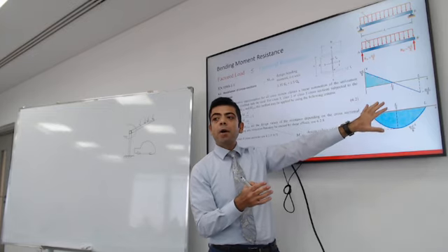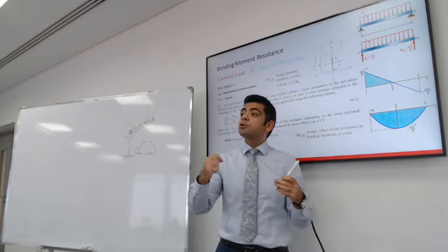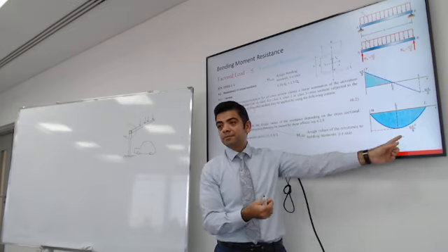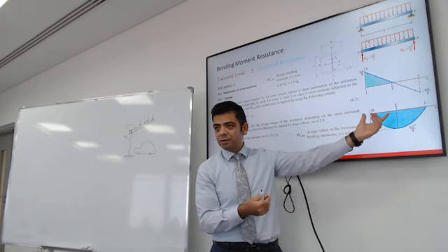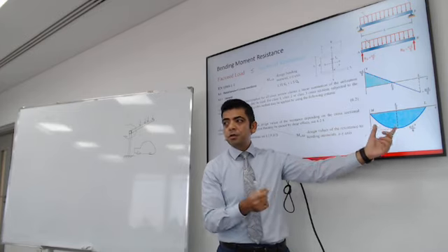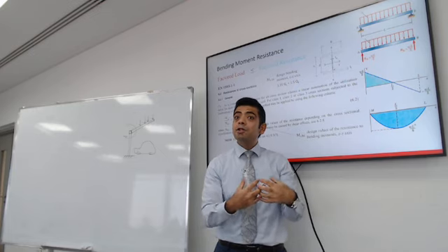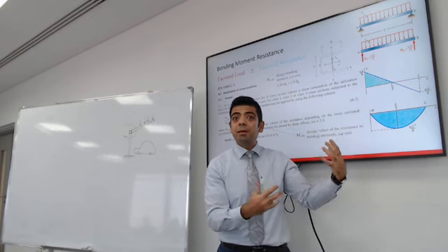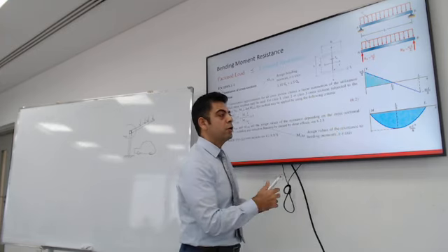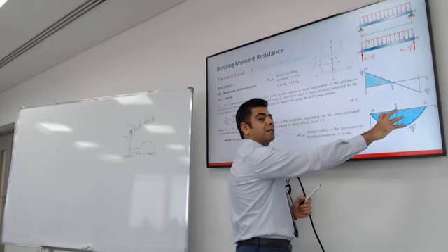All right, so now I know the applied load. I need to design this beam to be strong enough to withstand the factored moment. So how much is the moment on a simple beam with distributed load? W L squared over 8. So very quickly, first step, you can calculate the demand. How much moment is applied on the beam? You can get it from dead and live. Now, to design the beam, you need to choose a section that has a bending capacity bigger than the applied load.